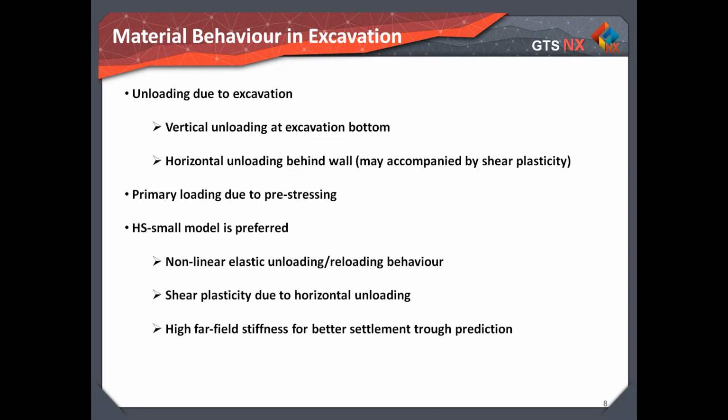Also, the linear elastic model tended to overpredict the movement of the toe of the retaining wall. Thus, a constitutive model which incorporates nonlinear elasticity, particularly at small strain, should be used in these circumstances. When choosing a constitutive model, the following aspects need to be considered: soil nonlinearity, actual resulting strains in the ground due to excavation, and technique for determination of ground stiffness.